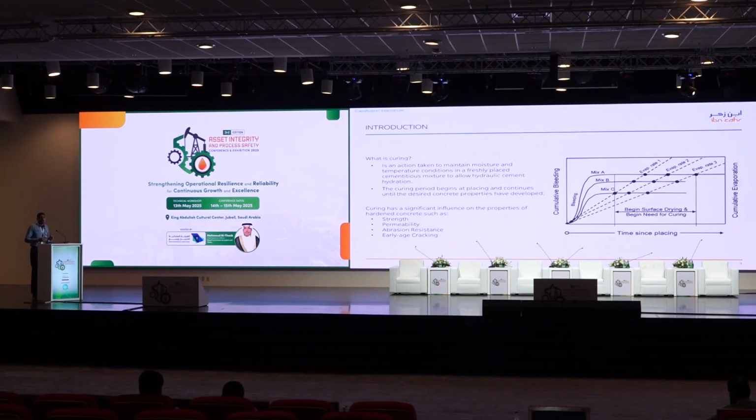The bleeding evaporates the excessive water from the concrete, and it depends on the concrete mix, which is why it takes from 1 to 3 hours. After that, the curing starts. It creates a hydration process inside the concrete, which creates heat and builds the bonding between the concrete particles.